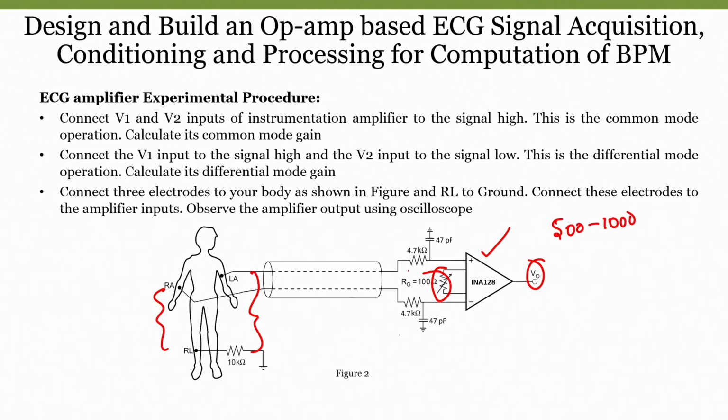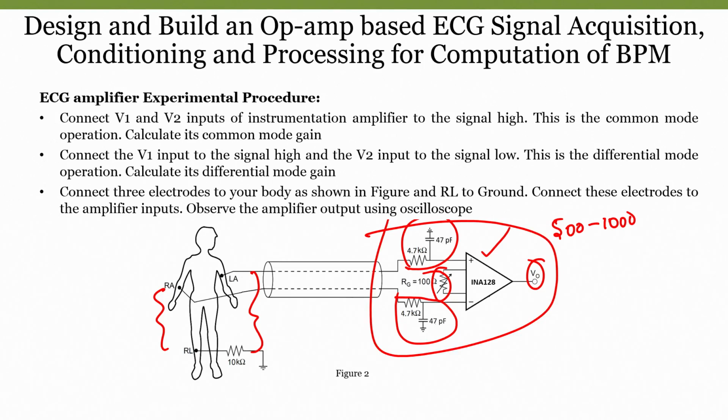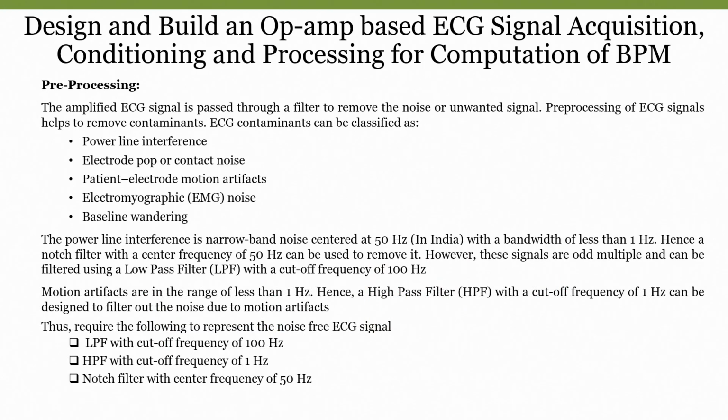Now, what is the use of this resistor and capacitor? This acts as a low pass filter. Any noise coming from the input signal will be removed. So, this circuit is the complete instrumentation, or amplification, stage of an ECG signal. In this experiment we will take this particular block to the last. Once we finish all the filtering circuits and other parts, we will come back to the instrumentation amplifier, check the difference between the instrumentation amplifier and the differential amplifier, and then interface it.